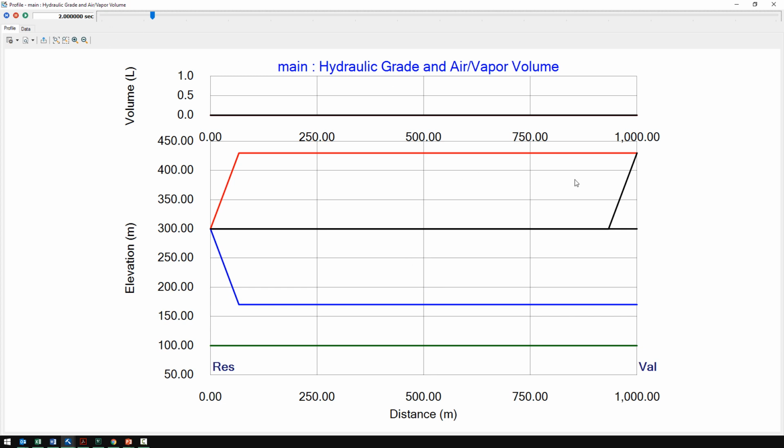So when that pressure wave has then reflected back to the valve, as I won't call it a low pressure, but it's reflected back with the same amount. So we're back down to the initial pressure, but once that hits the valve, it then reflects off the dead end, because the valve is a dead end, whereas the reservoir is an open reservoir. In this case, it's reflected back as a negative pressure wave.